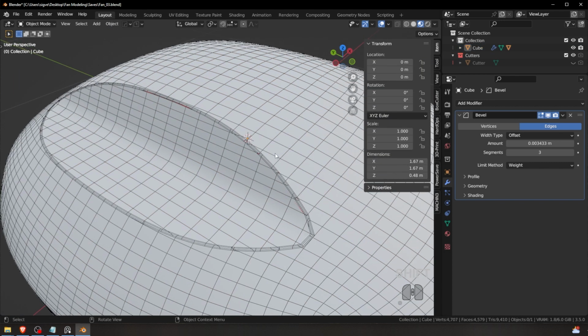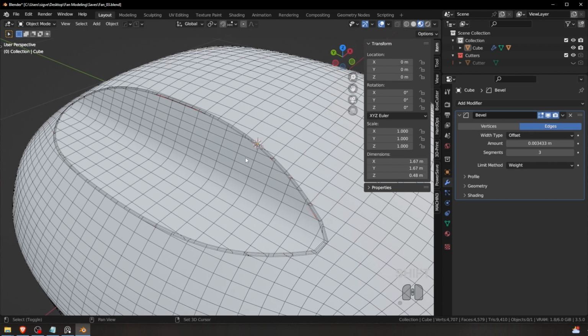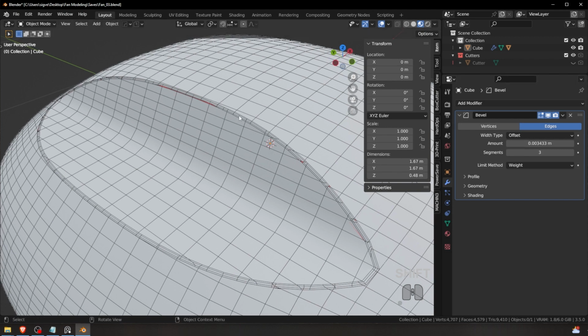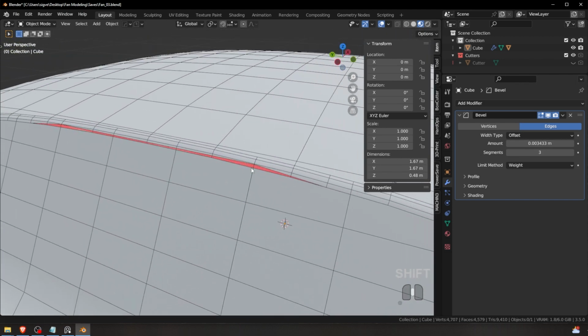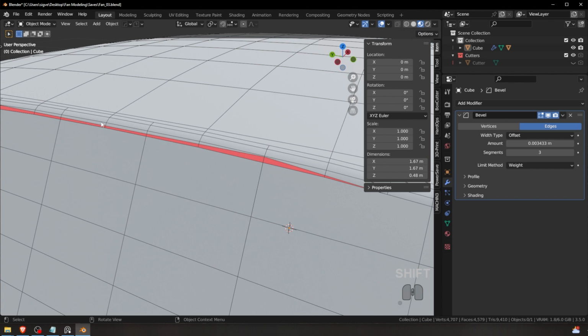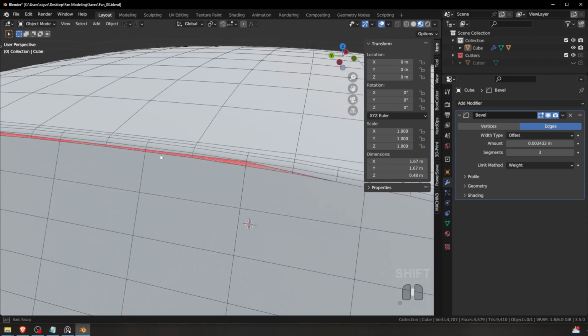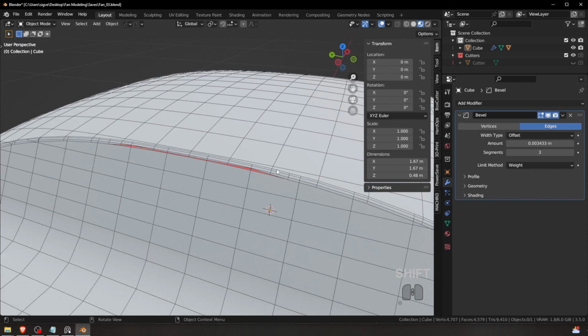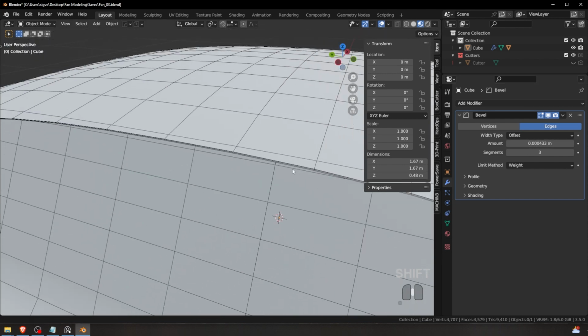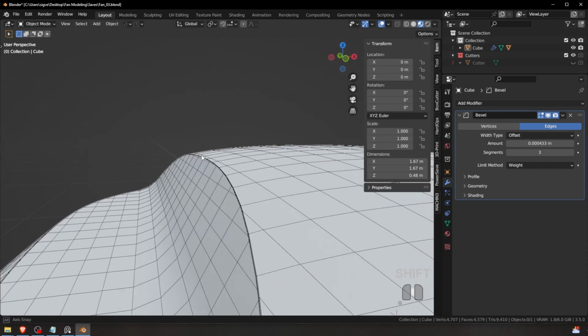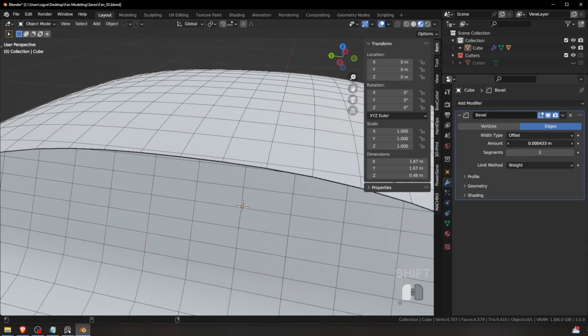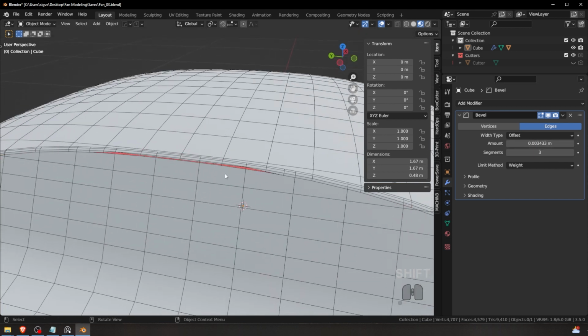So this is one type of error: the whole edge across not being picked up by the bevel. And now the other one is overlapping edges, like I said in here. They get overlapped. You remember I explained that this basically gets overlapped. To fix that, we can reduce this amount. That's one of the ways it fixes that, but I mean we need a bigger bevel. This is not going to work. So we need something like this size of a bevel.